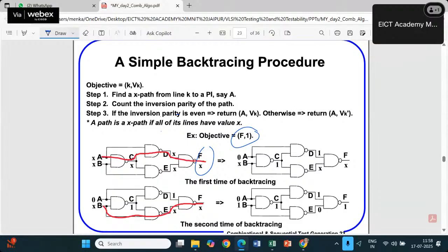We came to know that faults are only added at the fanouts and input sets. So here the faults will be for these 4 lines plus these fanouts. These are the fault sites we have to consider. So a total of 8 fault sites are available, so the maximum number of faults can be 16. In this particular case, the maximum number of faults available can be 16 with the help of the checkpoint theorem.